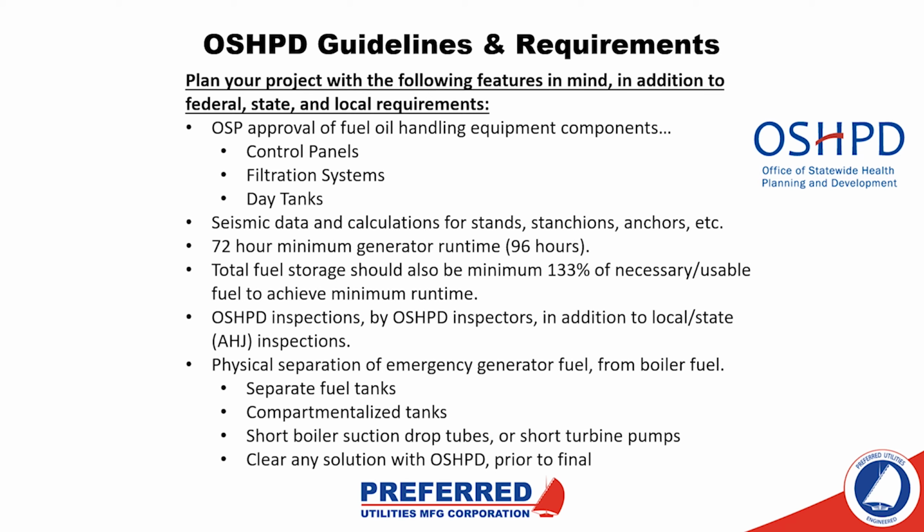So we'll calculate out the minimum runtime combined with the actual available or usable fuel, not the nominal capacity of the devices, but the actual usable fuel, and make sure that that's at least 133%. That ensures that there's enough for the minimum runtime, as well as fuel for exercising generators, testing, that sort of thing.